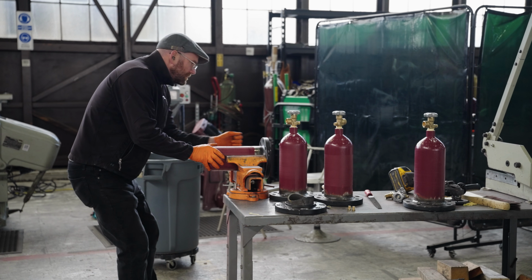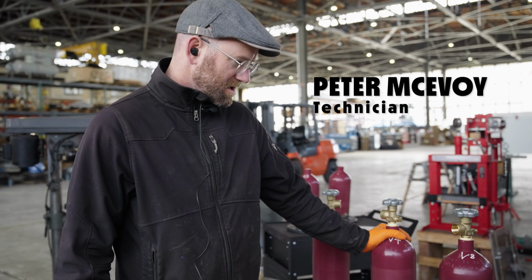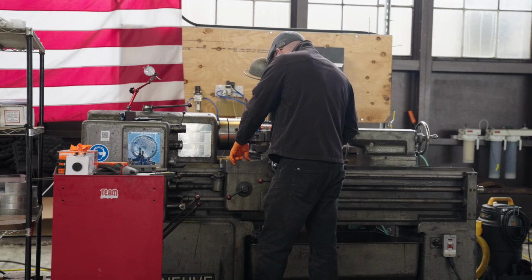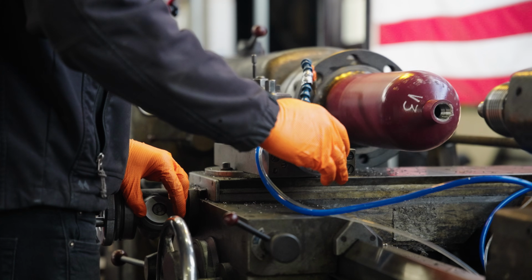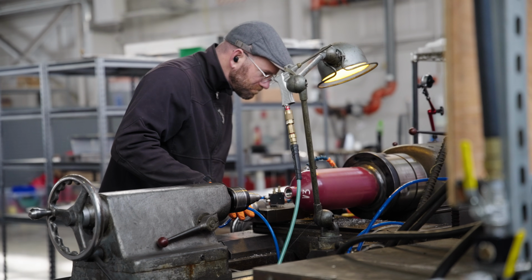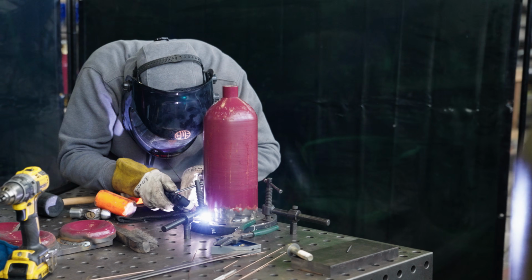Right now we've finished welding most of these boosters together. There's a flange with a gas cylinder, and then we're going to hook these up to hydro test them outside. They're pressure vessels, so they need to be tested with a safety factor of 1.5 times our actual use. So we're going to be testing these to 1300 psi. We use them at 850. And over here we're welding a few remaining ones together.